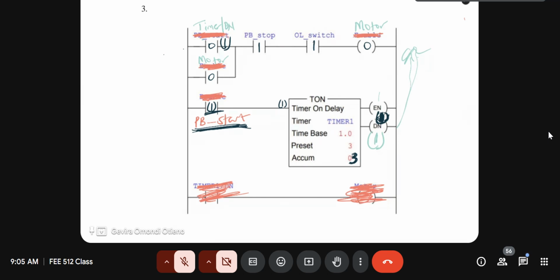And so then the way you connect them sequentially would require an enable bit on that side, but we don't necessarily use it as an output. Yeah, it's the done bit that's considered the output of the timer, not the enable bit.